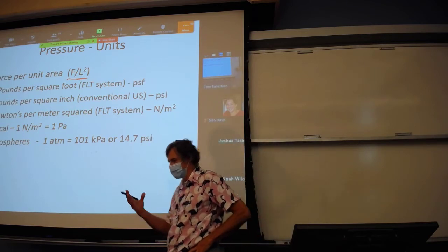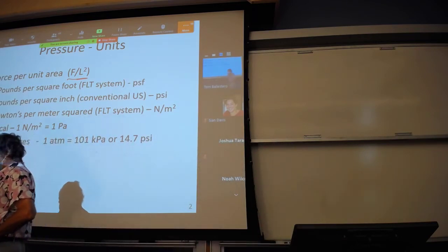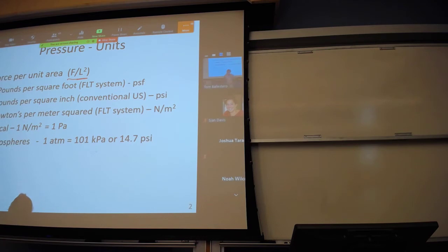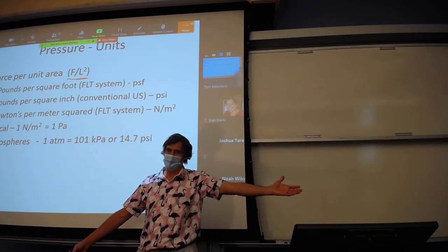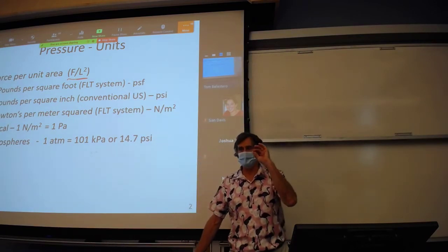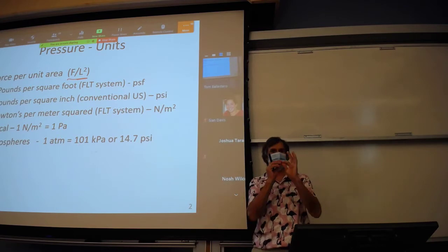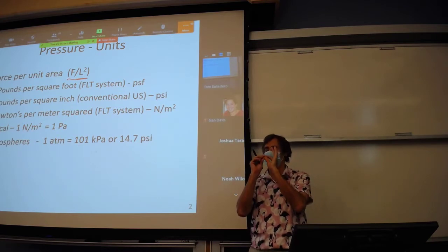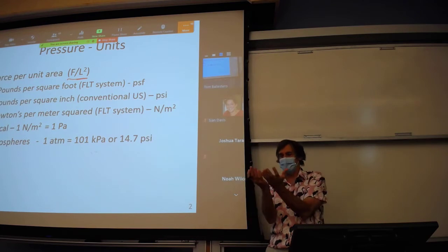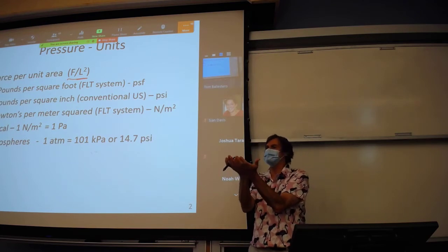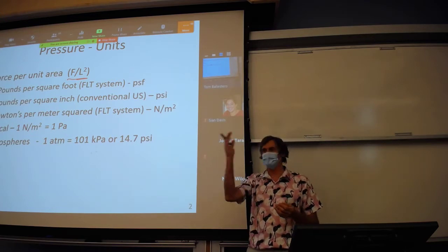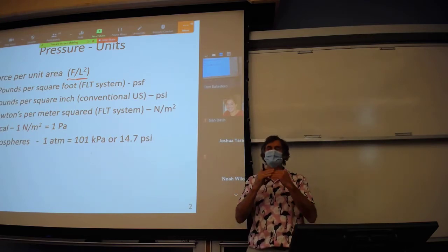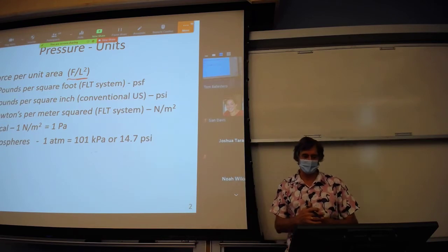And then the other thing, last time we started off talking about pressure measurement datums. And we recognize that there is the absolute pressure measurement datum and there's a local datum. Local datums for pressure are all zeroed. The gauges are zeroed on local atmospheric pressure. So if I took a gauge in this room, it would read 0 right now. Then if I put it onto a pipeline, I could see if the pressure was something different from that 0, different from local atmospheric pressure.